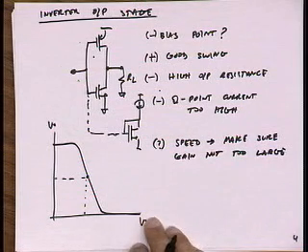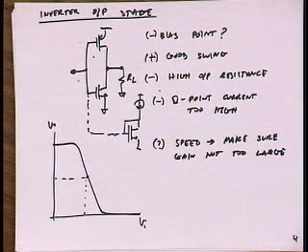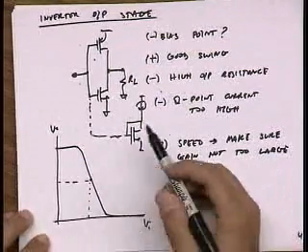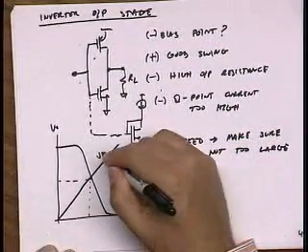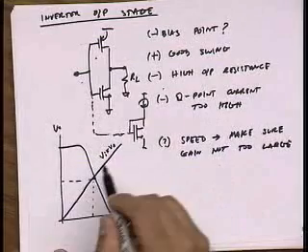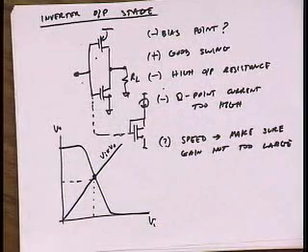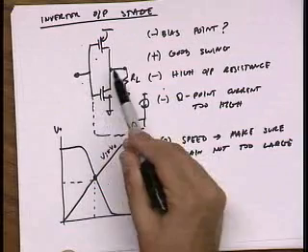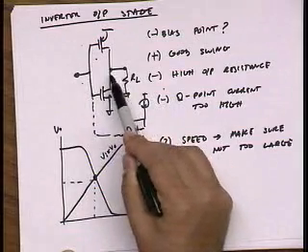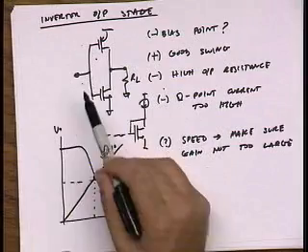Okay, so let's talk about how to solve the biasing point problem, first of all. One way to do it is just to observe that if you consider the curve V in is equal to V out, then this intersects this curve at a pretty good point, right around the trip point of this inverter, right? So one way to bias it would be to have some kind of servo loop that takes the output DC voltage and forces the input voltage to be the same. What's a good way to do that? A very simple way of doing that.